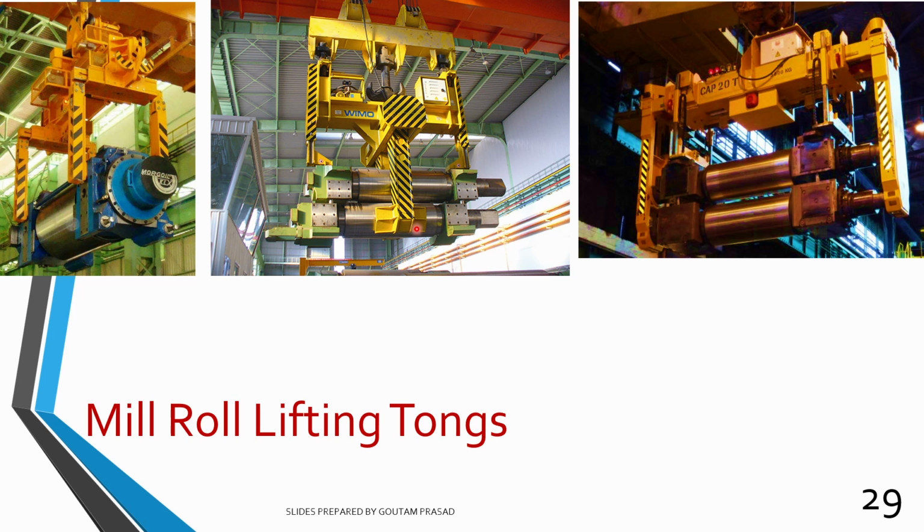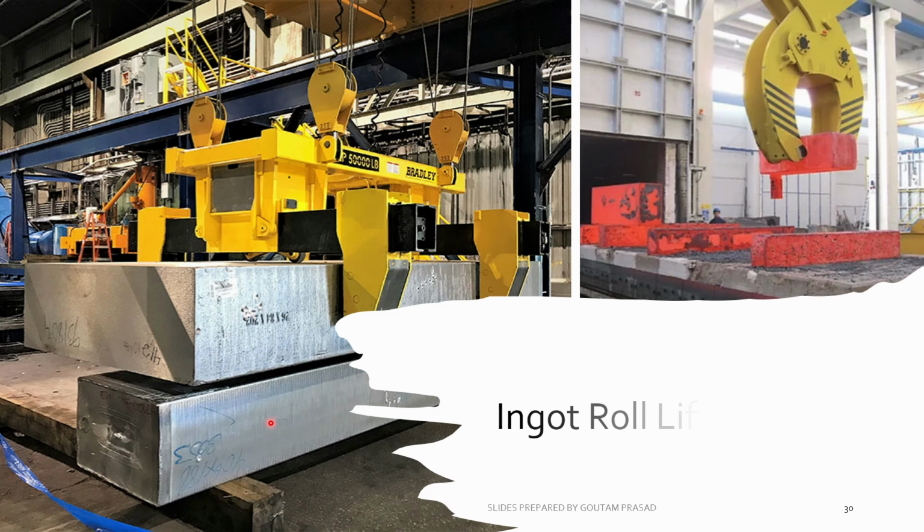So the entire arrangement has been made in terms of tackle so that the whole thing is lifted safely and transported to a place where it is required. So here also the entire stand of the roll is being lifted. An ingot is being lifted in this picture. Here also an ingot is being lifted. So the ingot lifting tong is designed in such a manner that it is supported at four places with the help of ropes. You can see three are visible. One is hiding behind this seat block. So the whole arrangement is like this.